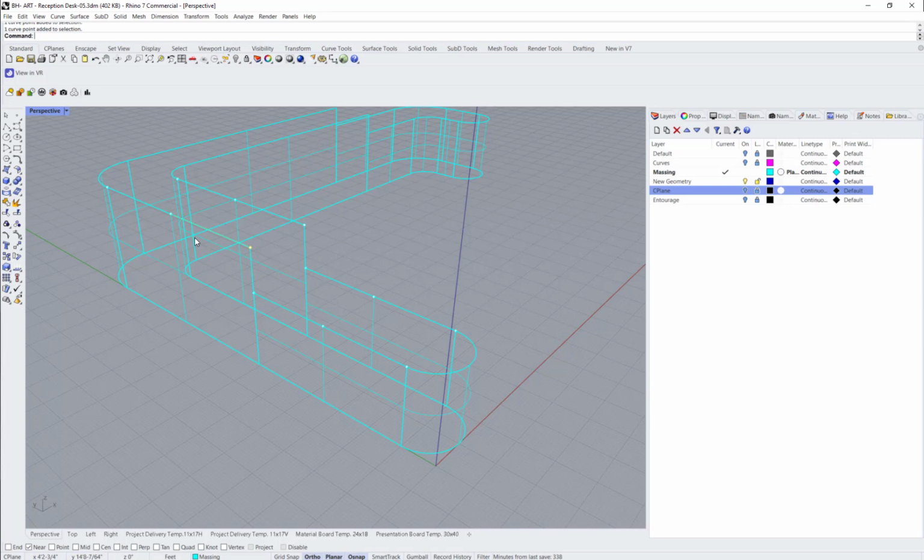To fix this, we can adjust the degree of the control points by using the command change degree. What you'll want to do is follow the prompts by selecting the curves you'd like to adjust the degree and press enter when you're done. We want to adjust this degree 2 curve into 4 points by making it a degree 3. So here you'll just add the number 3, and then you'll see that we now have 4 points. Therefore, a degree 3 curve, which is a minimum of 4 control points, can each have a set of tangent directions without affecting the tangency at the other end.